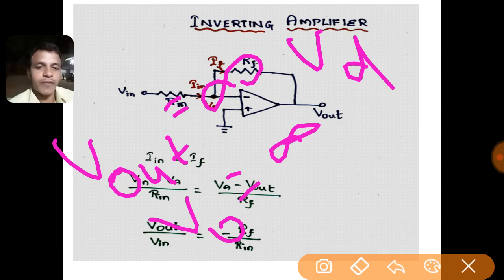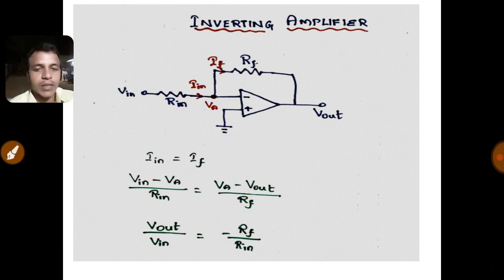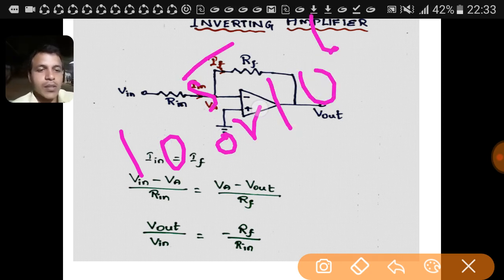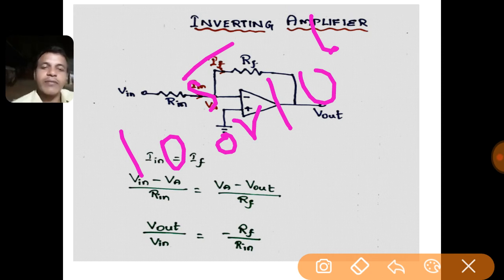A practical operational amplifier does not take the value of gain as infinity. Instead, it takes the gain as a very high value in the range of 10 power 5 or 10 power 6. Even then, even if the difference of voltages between the two input terminals is very small, since the gain is very high, the amplification is done in a very greater range.